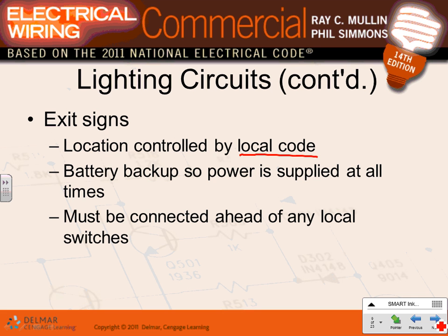We put one at every exterior door of a building. Typically, if there's a hallway, I believe every 100 feet, in big hallways, you put one. At the top of every stairway that takes you down, you put one, if it's a bigger building. So 100 feet, every stairway, every exit, and then you kind of walk yourself through the building. If you have a multi-occupancy room, like a conference room or assembly room with 100 people or more, you put exit signs on at least 2 doors that come to this assembly room, by building code. So that's where we put our exit signs.